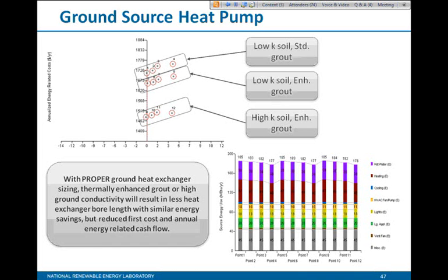I think this problem existed for the heat pump as well as two-stage AC. In the heat pump and AC categories, we actually use EnergyPlus and revised the input based on the EnergyPlus model. But in the case of ground source heat pump, everything is DOE-2 based, because EnergyPlus is still lacking in proper modeling of ground source heat pumps.